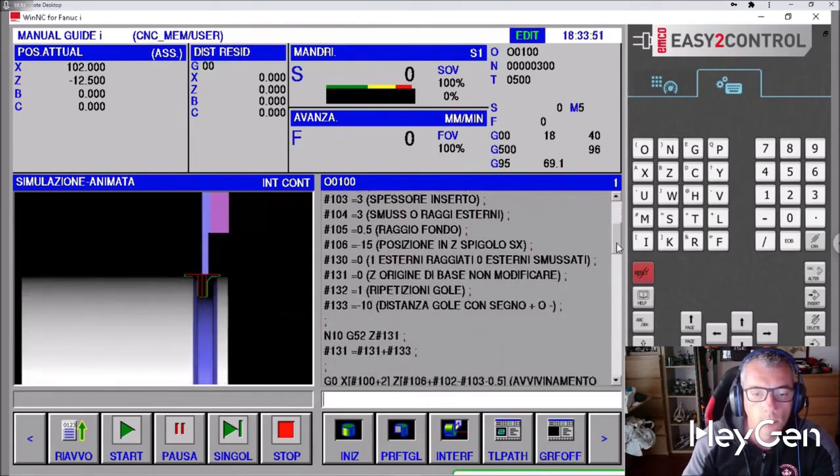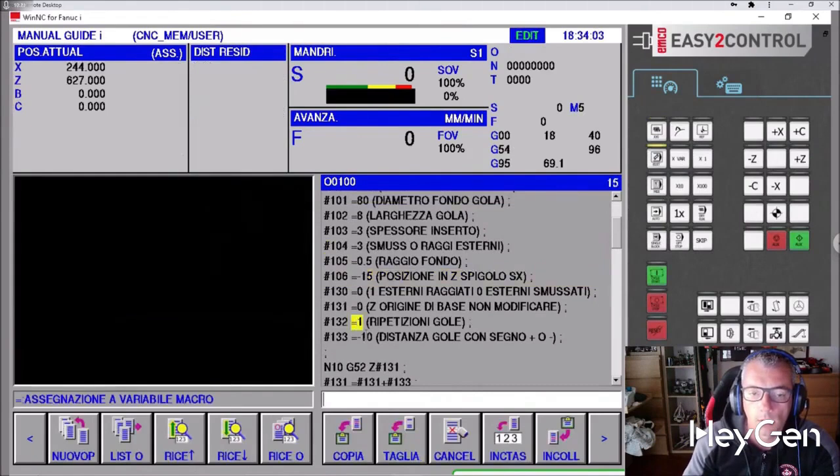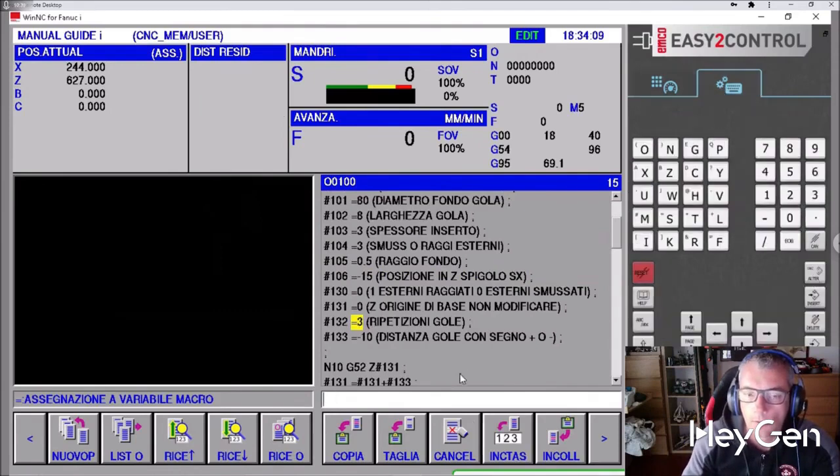Now I want 3 grooves to be incorporated into the design. So let's go to Edit, and we go to Repeat Grooves, and we set it to 3. Let's set it to a distance, since we made it approximately 8 at least, -15.